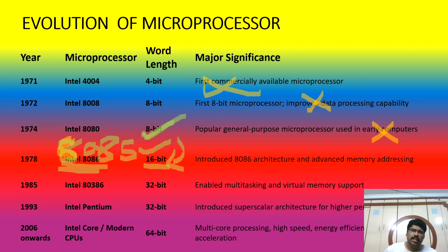And there is no pipelining concept. Pipelining means one instruction is in execution, another instruction is decoding, and another instruction is fetching. Like this it happens, then it is considered a 3-stage pipeline. In some processors we have a 5-stage pipeline. That means multiple instructions are under operation simultaneously. One instruction may be fetching, another may be in the decoding state, another may be in the executing state. This automatically reduces the number of clock cycles required to execute an instruction. It automatically increases the speed of operation. But such a pipelining concept is not present in 8085.